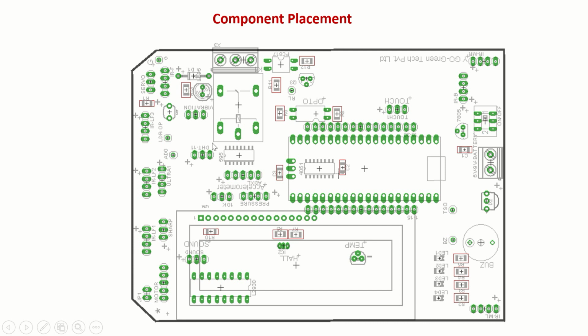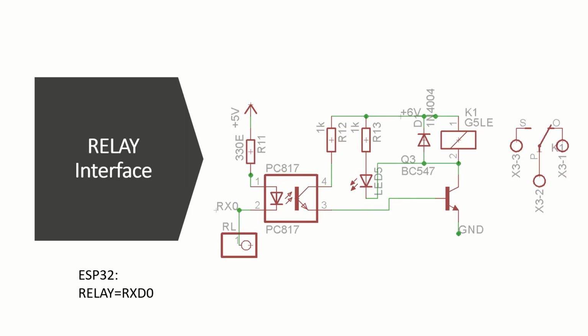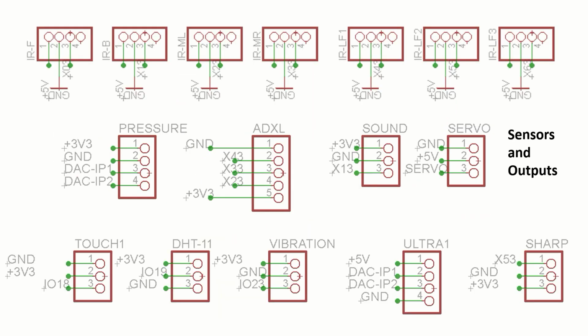Okay, so quickly, instead of soldering all these sensors, let's not even use the DHT11 sensor. We will use this DHT slot as a switch. If you carefully look at the connectors in DHT11, out of these 3 pins, the center pin is the input pin, GPIO19.